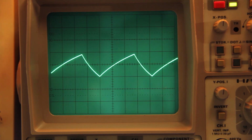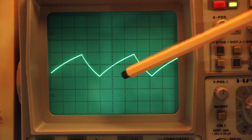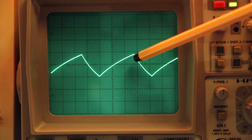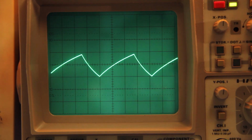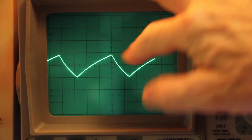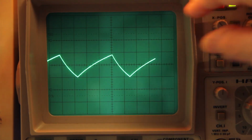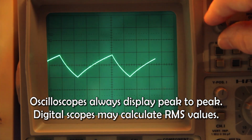So, for example, the voltage we have set right now is 2 volts per division. So here we have 2 volts, and this waveform reaches a positive peak of about 1.4 volts, because it reaches this point, and the negative peak reaches negative 2 volts.